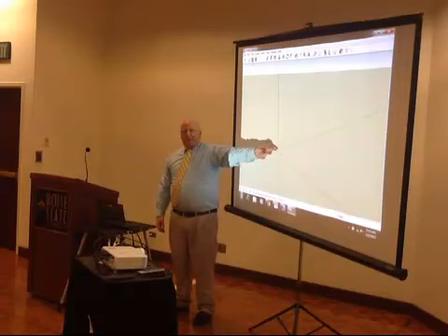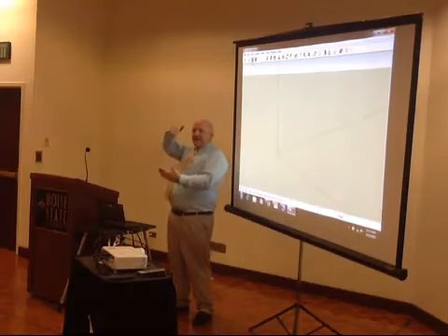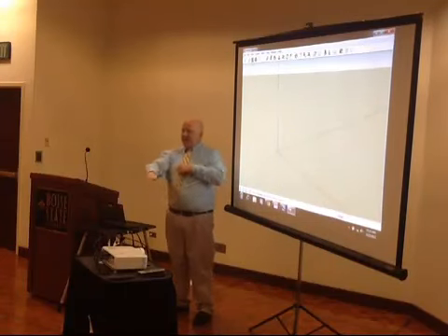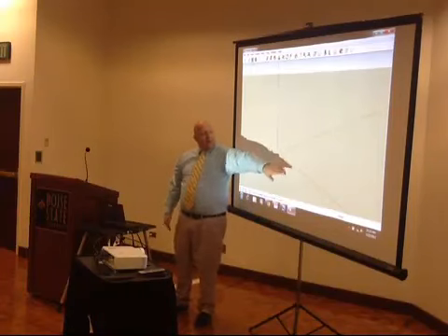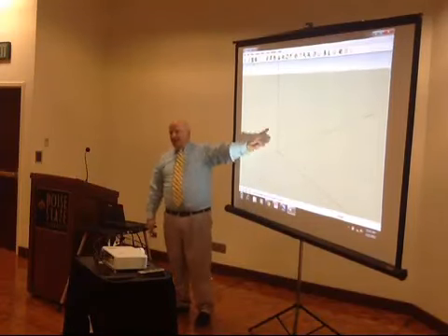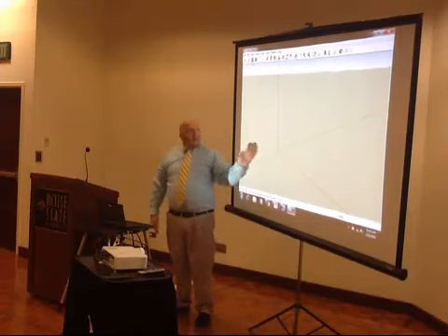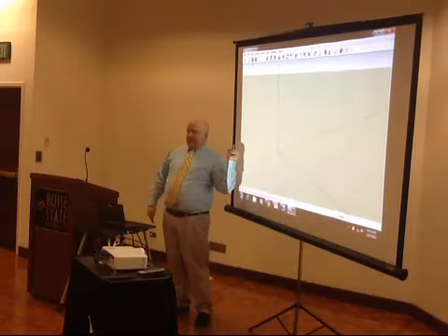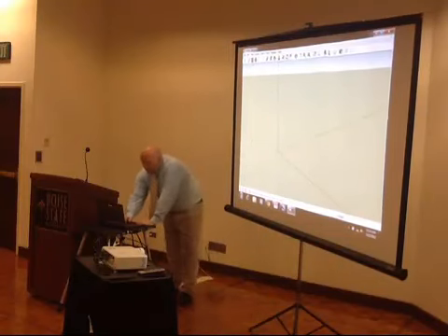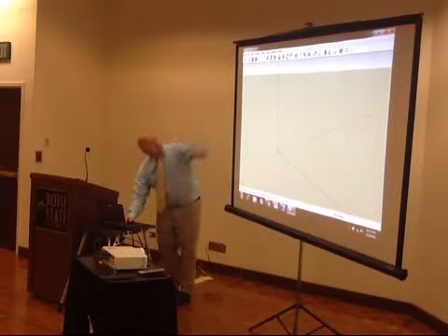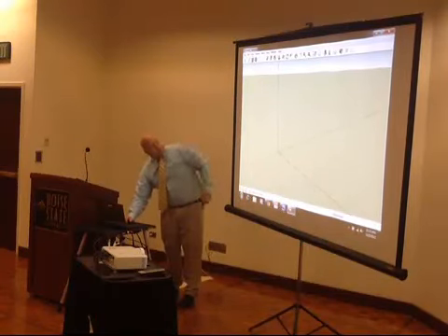This is a three-dimensional view. It's called an isometric view. We're standing up and to the right, looking down. We have a horizontal axis in red, a vertical axis in blue, and a depth axis going back in green. What I want you to do is click once on the rectangle tool up here.